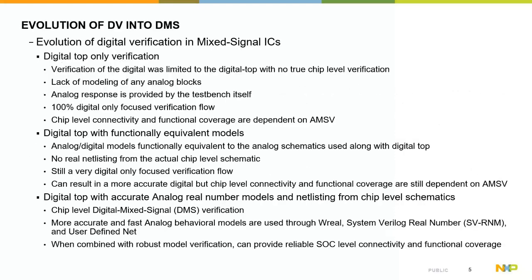So let's look at the evolution of DV, talking in terms of verification of mixed signal ICs. Traditionally, if you go back a decade or so, digital DV on mixed signal ICs mostly started with verification only at the digital top, and there was a lack of modeling of any of the analog blocks, and any of the analog response was provided by the test bench itself. It was a 100% digital-only focused verification because none of the analog was modeled.